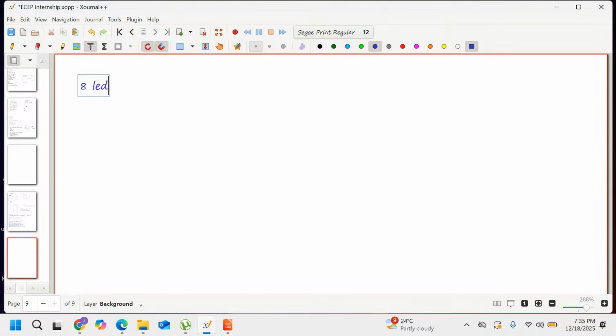We are going to program 8 LEDs, and these LEDs are connected to a microcontroller via Port B. Port B is an 8-bit port, and this can be controlled via the data direction register, which is nothing but TRISB. This much information we have now.